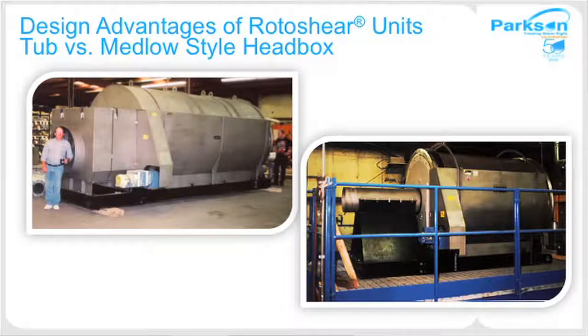One of the main advantages of the Rotoshear screens is the head box design. Our head box design is very unique compared to anybody else in the industry. We offer custom designs per application. We have the top style and Medlow style head boxes. The upper left corner that you see is our top style head box, with a big box in front of the screen, which has the baffle arrangement in the front. The bottom one is the Medlow style head box, typically for industrial applications, and it doesn't have that baffle arrangement. Why is this important?